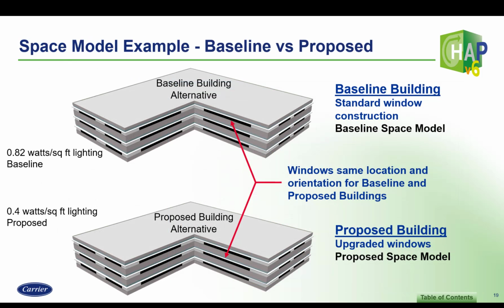Many of us have been using space models for quite a few years and are not even aware of it. For energy analysis, we often compare a proposed building versus the baseline version, which is almost the same as the proposed, but may vary in certain areas like overhead lighting power density and window construction, just to name two typical ones. With that in mind, the proposed building would have a space model and the baseline building a slightly different space model.